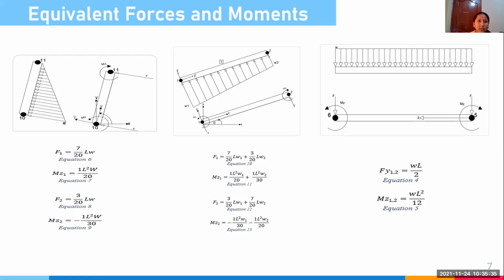As a finite element, it requires the equivalent force and moment vector for determining the displacement vector. We simplified the forces into punctual forces at the joints. For this, we used the equations for this type of geometry loads. Next.